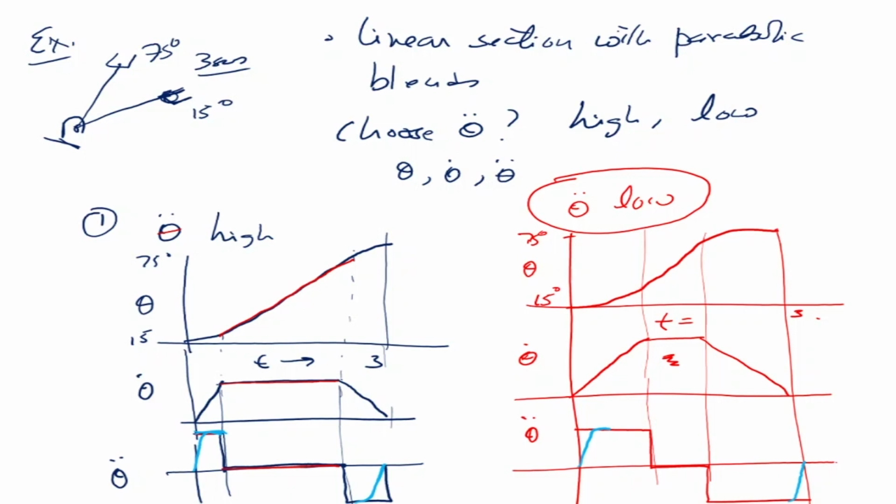Now we have said that one of the constraints that we have put is that the manipulator joint moves from one position to another position. This is a link, and we have another one here like that. We said that it is going from one location, one angle theta naught to theta f in some time tf. Okay, but by doing this we have no control. There will be one trajectory fitted for this joint, and another trajectory fitted for this joint, cubic polynomials. But by doing that we have no control over what the end effector will do.